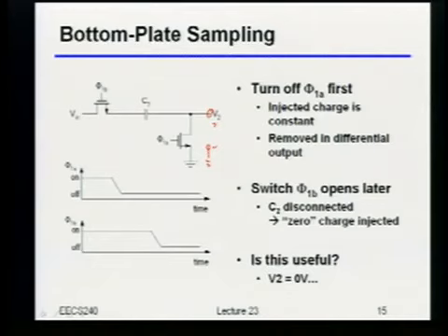I guess just across the cap. Yeah, exactly. I'm just storing the input signal across that capacitor right there, right? So in order to actually make this useful, rather than measuring the voltage across here, all I actually have to do is measure the voltage across that capacitor. Or rather, basically use the charge that's stored in that capacitor to actually affect my output.